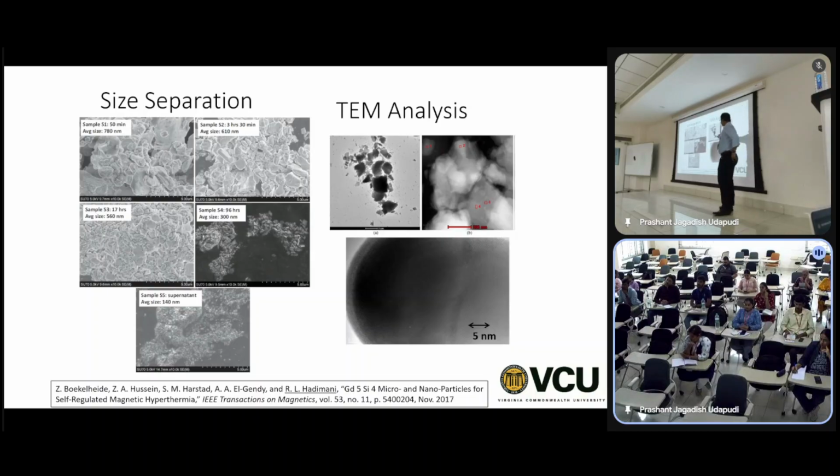And these are TEM images. So here you can see this is a particle, and you see this is amorphous, this is crystalline, right? These are signatures of crystalline material. These are basically your atomic stacks. Okay, so here it's a big particle that electrons did not go through.